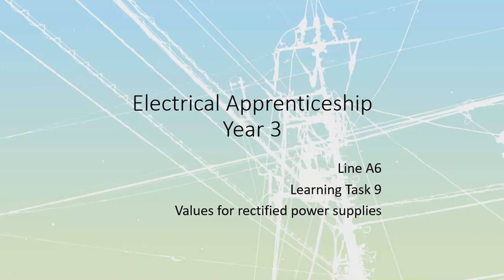So we will use massive values of DC, and in a lot of cases we're going to have three-phase systems, because where we use these big values of DC is going to be in places where we've also got a lot of pumps and motors and things like that. So we're going to come from three-phase, change that into DC, and then carry it around our plant in what we would refer to as a DC bus system, where we're then able to take it off and use it to run the actual DC loads that we see ourselves using. So let's go through our examples.